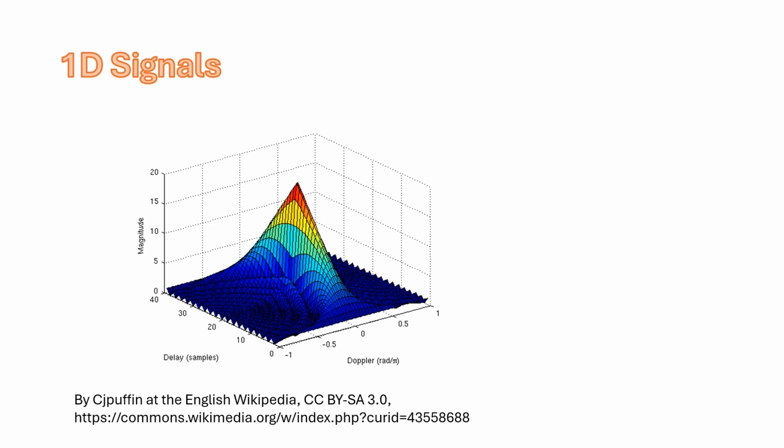This is a square pulse, and so its convolution with respect to itself is what's here on the zero Doppler axis, where you're just integrating the convolution of the pulse with respect to itself. And as you go off, you're taking the Fourier transform of the shifted pulse, and you see these kind of fringe modulations along the Doppler axis that would be the same as what we saw in this density plot that was on the introductory slide.